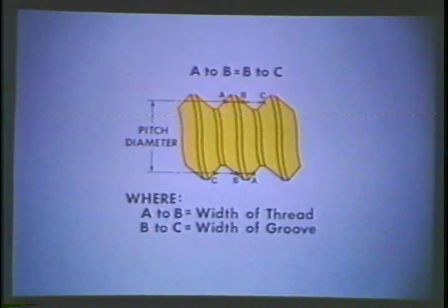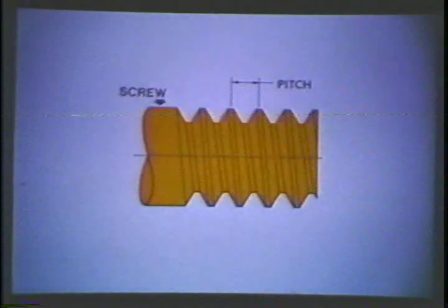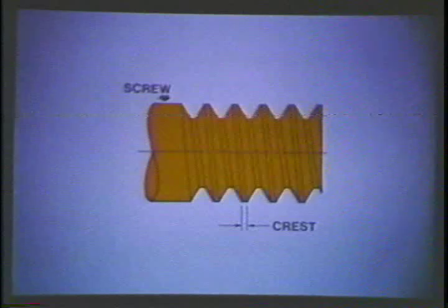This was easy to do because we were working with a drawing. On a real bolt, the pitch diameter is an imaginary line that meets this criteria. Now that you know pitch diameter, another term, pitch, is easy. As you can see, it's the distance from peak to peak. Speaking of peaks, that's the wrong name even though it seems to fit. The correct name is crest, and that fits also.